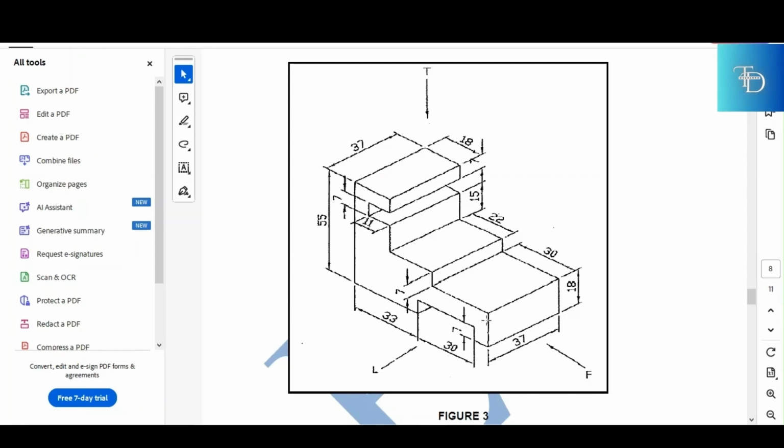And then, are you gonna see that side? No, you're not gonna see that side because that's on the left hand side. Are you gonna see that surface? No, you can't see that surface because it's on the top side. You're only gonna see that surface when you are looking at this thing from the top side. So now you already confirmed that this is what you're gonna see when you are looking at this thing from the front. So every other surface that is parallel to this surface is what you're gonna take from here, and you're gonna draw it where you're supposed to put your front view.